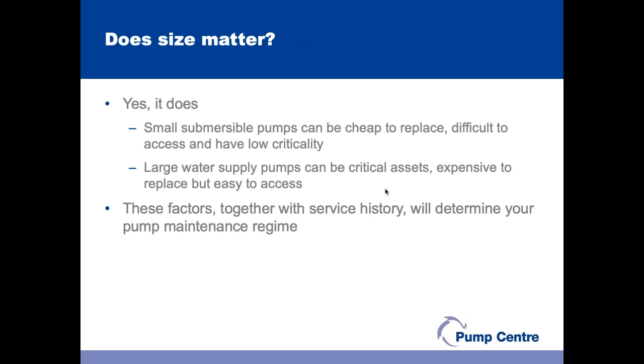Does size matter when it comes to how you're looking at maintaining your pumps? Well, yes, it does. Small submersible pumps can be relatively cheap to replace. They can also be quite difficult to access because they're down wells, and often they are relatively low on the criticality scale. Often because there'll be a standby pump there anyway.